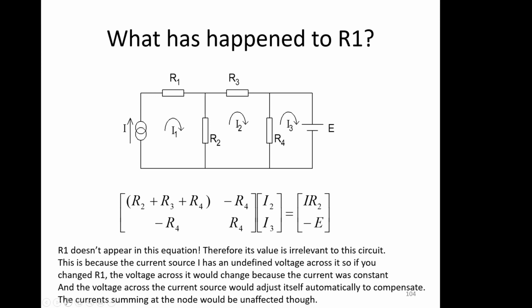But what has happened to R1? If we look at this matrix equation, there's no R1 in it. There's no R1 anywhere in here. R1 doesn't appear in this equation. Therefore, its value is irrelevant to this circuit.